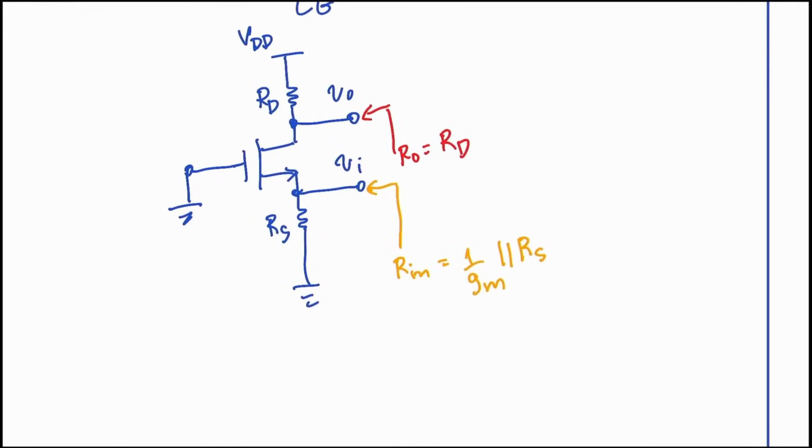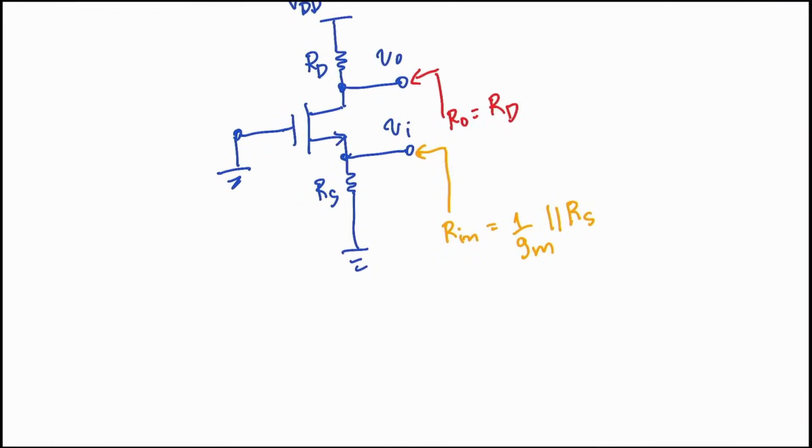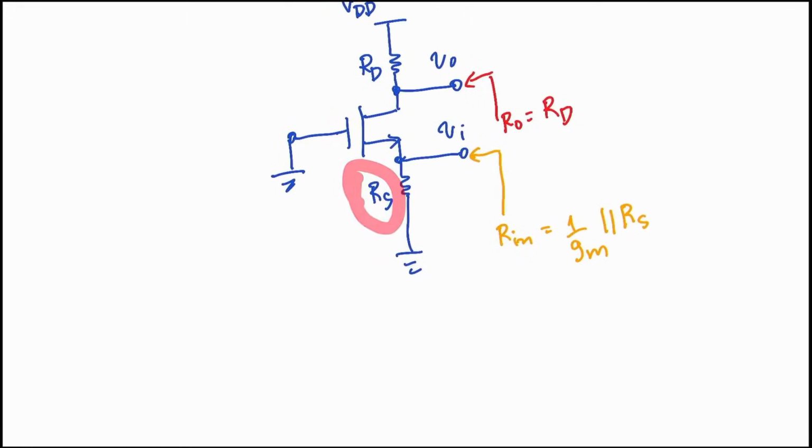I hope this is understood, right? Because in the DC bias circuit, we have to make sure the MOSFET is in the saturation region. It's necessary to have current flowing like this, so it has to go down here to the ground. In that example, we didn't have this RS, the topology we were working with. We connected directly to the R signal here, but in reality, we have to make sure the MOSFET is in the saturation region first, right? So there must be a current path to the ground for it, which is through this RS component.